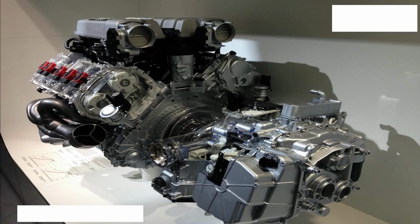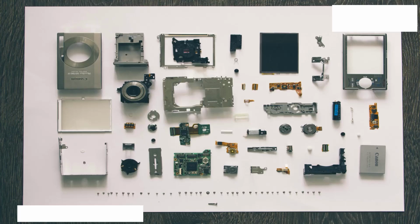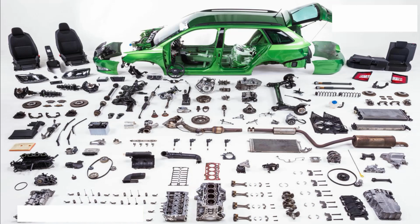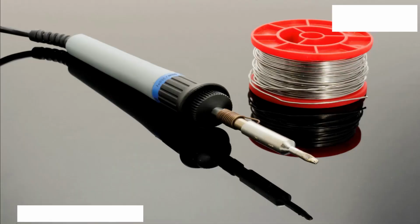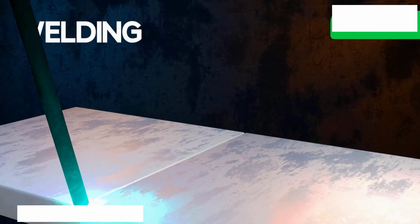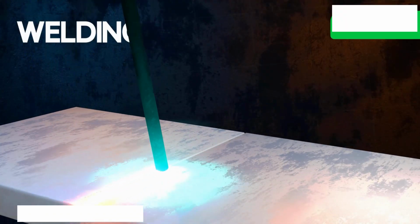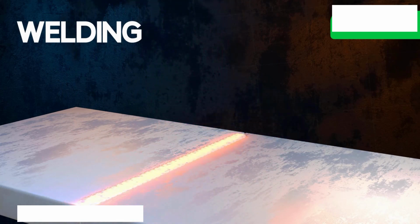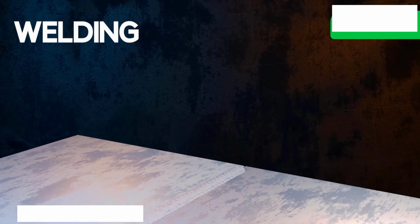There are many products we encounter daily that can't be manufactured from a single item. There are a number of components involved in it to make the product useful. Those are combined using these joining and assembly processes. There are different types like welding, soldering, brazing, and mechanical fasteners like nuts and rivets. In welding, two or more parts are heated and melted or forced together, causing the joined parts to act as one. The working principle for brazing and soldering is the same, but the difference is their working temperature.